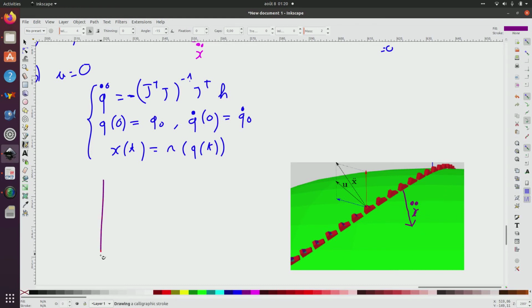So if I have here my Q space, Q1, Q2, this trajectory corresponds to a trajectory inside this space, so Q of t. I can choose the acceleration Q dot dot as I want, but I cannot choose X dot dot as I want due to the curvature.